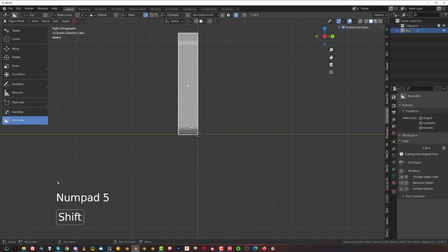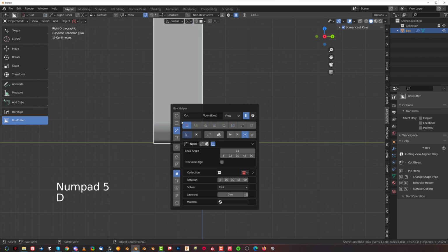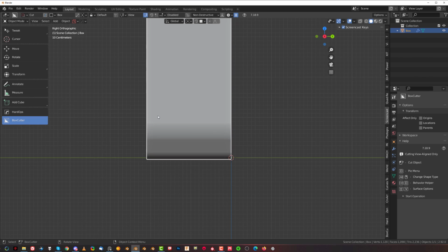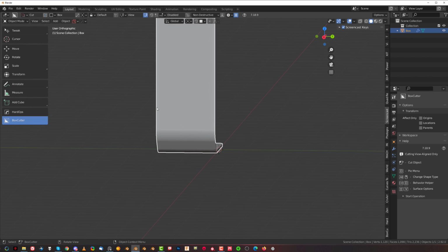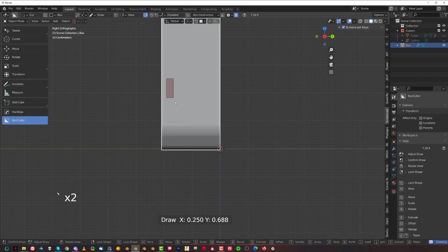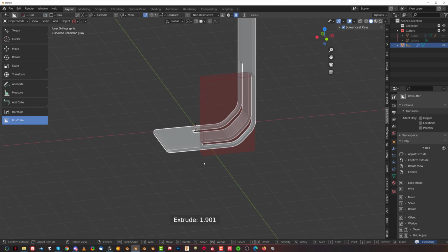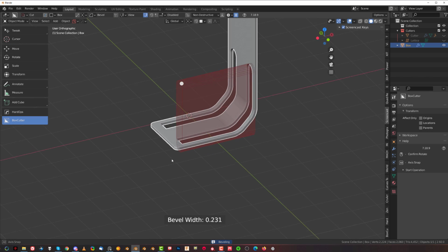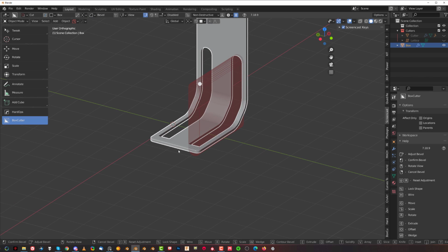Now go to back view, rear view, and let's go to the menu and box. Now remember we're mirroring from left to right, so I wanted to create a cut in here like this, maybe a narrow one that goes through up to here, and I press B for bevel. Now you see that the bevel will not bevel both ends.